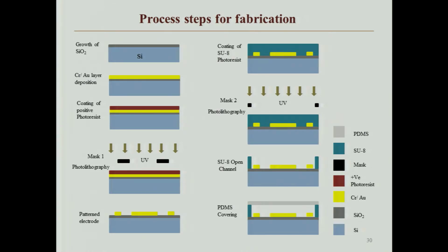So, now this is the complete fabrication process comprising the two lithography steps. After this, what do you have? You have one covered channel, inside that you have integrated electrodes, and on one side you have an input, and on the other side an output channel.